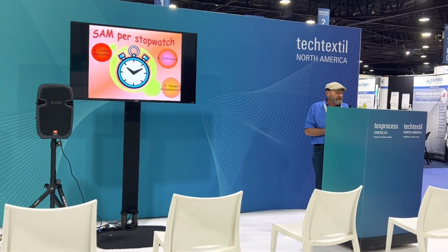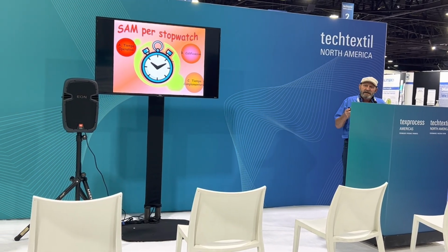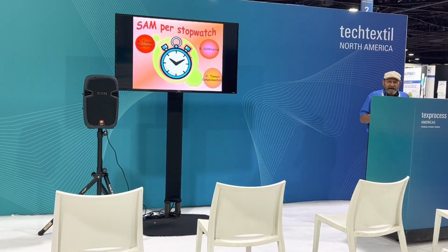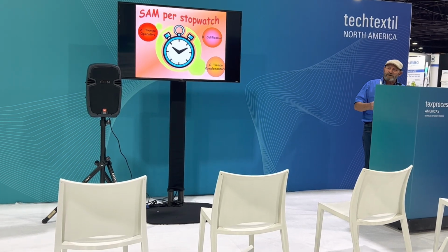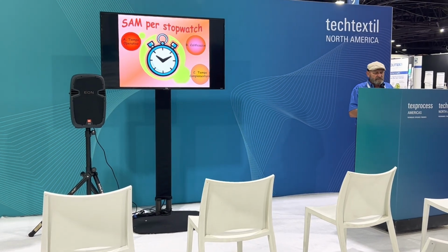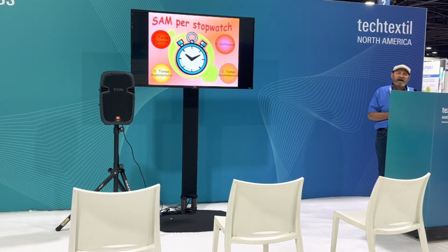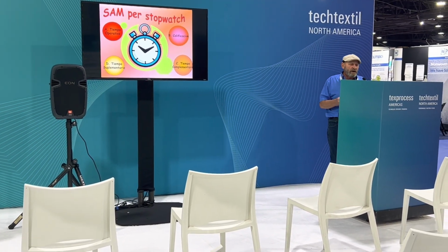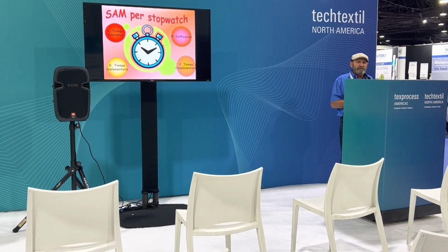Now, the time complement is actually time that you can add in order to make the operator run more than 100%. Some companies choose not to do this, but a lot of companies, if you want to use a high task or low task system, will put in additional time to bring that time value down. And then also you have your time for personal fatigue and delay, which is your supplementary times, and all these are required in order to arrive at a proper SAM.